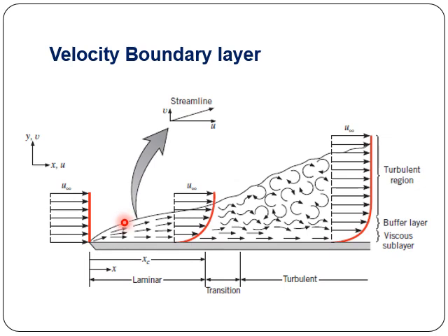So if u of the fluid, or velocity of the fluid, is equal to 0.99 u infinity, that is the free stream velocity, I get different points at different values of x. If I join those points, I will get a curve which is called the velocity boundary layer. So at the velocity boundary layer you will have a velocity which is 99% of the free stream velocity. Velocity of the fluid at any point on this velocity boundary layer is 99% of the free stream velocity.